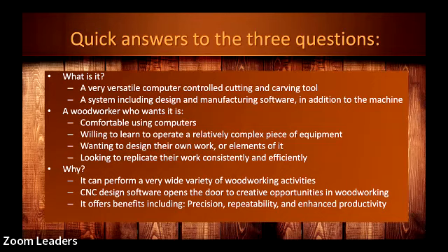The other piece, especially for folks that are involved in professional replication of their work for sale, or involved in toy drives or other things where there's a lot of product that needs to be reproduced, and hopefully with a certain amount of reproducibility, CNC machines are really helpful for that. You can cut multiple things at the same time. You can load different pieces of material on and cut them identically over time. We'll talk about the particulars of all of that in a little while. But for replicating work, it's a real productivity enhancer.